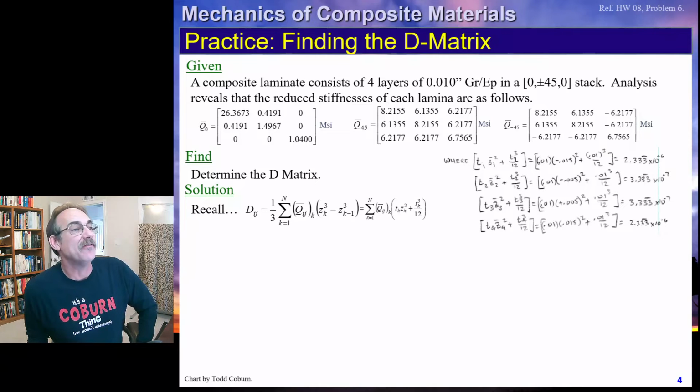So, as before, it is useful to use the same sketch we had where we have the thicknesses and the Z bars all identified, and then calculate this second term, this T Z bar squared term plus the T cubed over 12 term for each and every layer. As you see here, we see it for the top layer, the second layer, the third layer, the fourth layer.